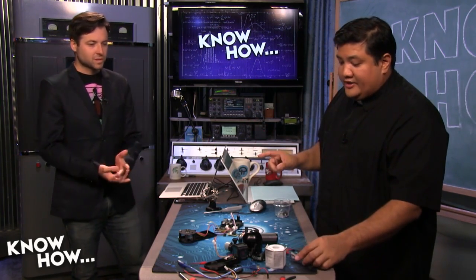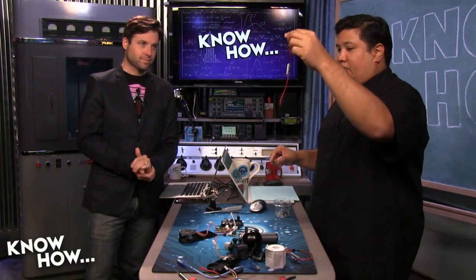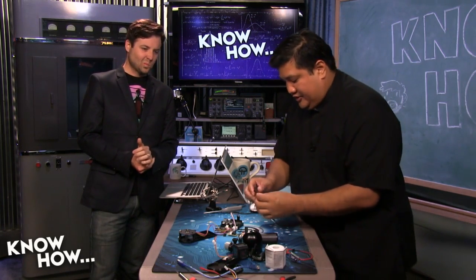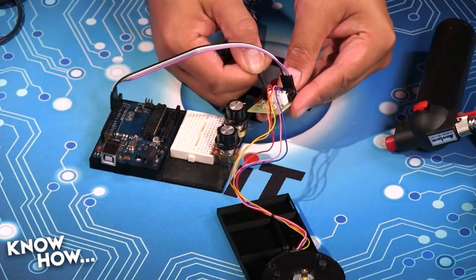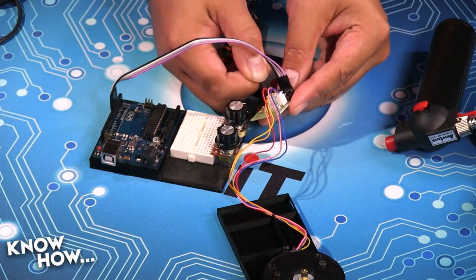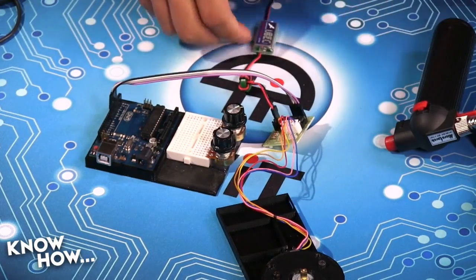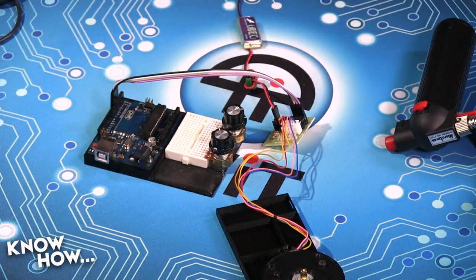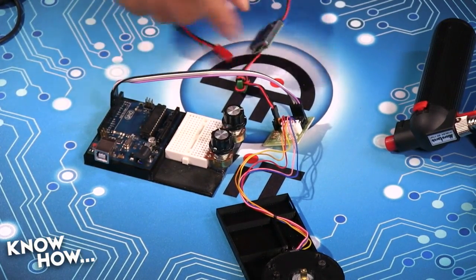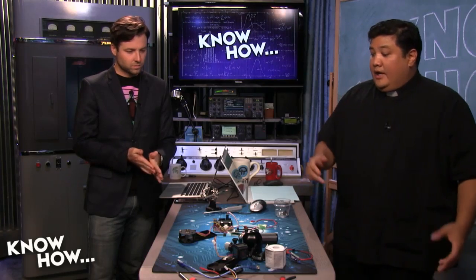Right. Now I just need to connect power, which comes off of my UBAC here that we just created. I'm going to go ahead and put power in. And like you said earlier, we're doing 2 separate power sources because we don't want to blow out the Arduino. So this Arduino is going to be powered off the laptop, and this is going to power my stepper motor. Cool.